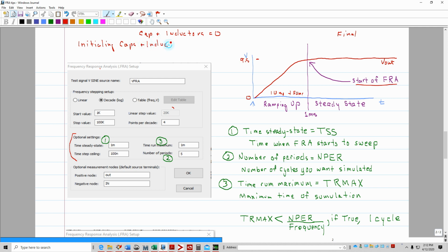The reason we did the IC equals 9.95 and also initialized the inductor, in this case my inductor was 150 milliamps, is that instead of the simulator starting here, the simulator actually starts with the values here. It doesn't start here, the simulation starts here, so it's already at the final value.